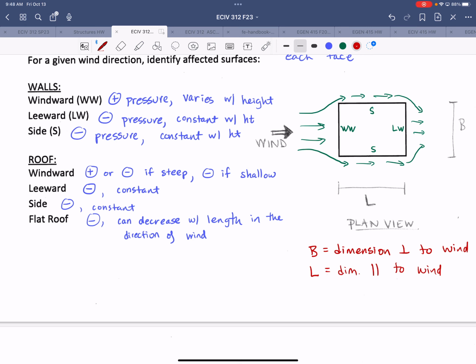We use a wind tunnel study where they create a scale model of the building and all of its surroundings for hundreds of feet around it, so that we can get a feel for how those extra structures affect it. A tall building upstream of the wind direction can cause peculiar effects like buffeting, where the wind just pounds on the building behind it.